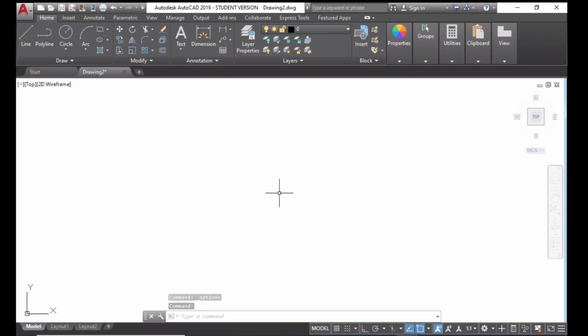The reason that we are making a template is because if you're making multiple drawings and you have already fixed the size of your drawing sheet, it's easy to open it up and do your drawing over that again and again. Once you've made a template, you can always reuse it. When you print the output from AutoCAD on an A3 sheet or an A4 sheet, you can set that in AutoCAD when you start making your drawing. Based on your company's or institution's requirements, you can make any template.